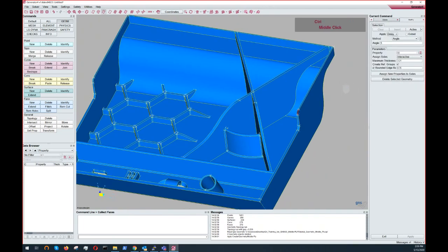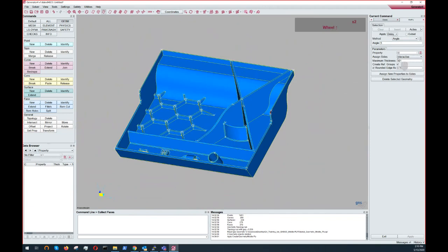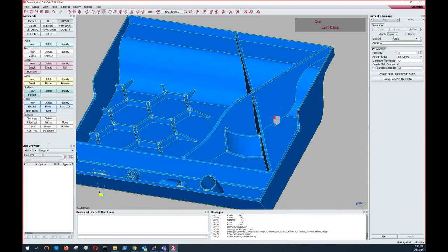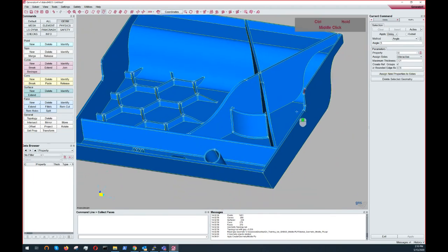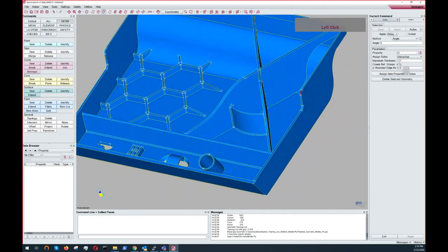So maximum thickness is, generator looks for pairs of faces in order to get the front and rear. So this is a maximum gap that it's allowed to be used. We have defined these default values as the most common ones that fit almost all the examples we had, but maybe you have to adapt them a little bit.